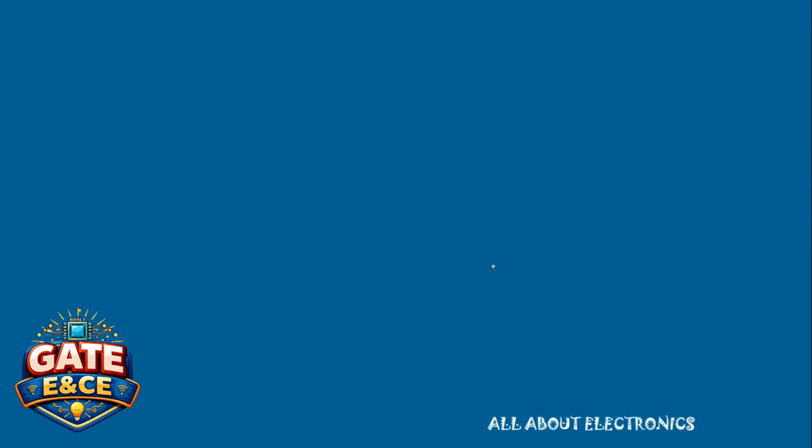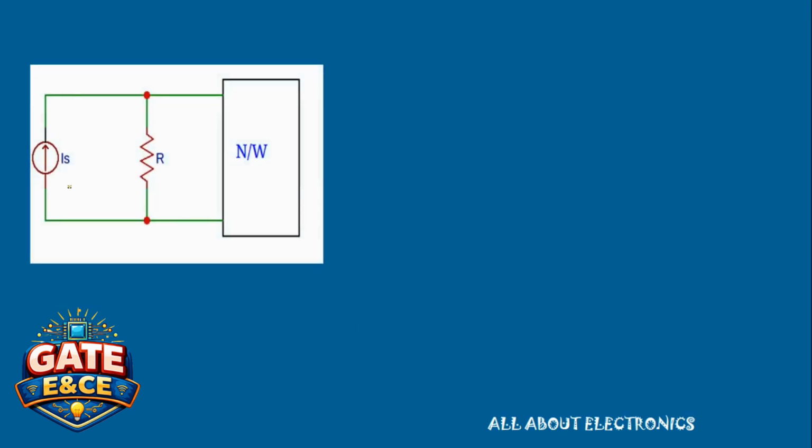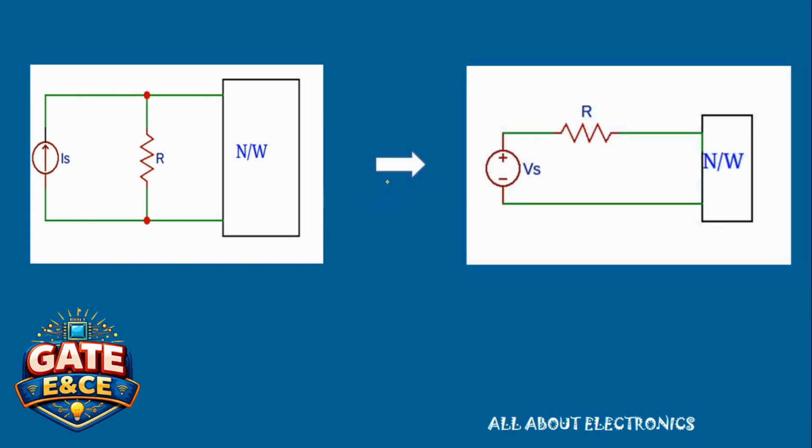Likewise, let's say we have a current source Is with a resistance R in parallel in any network, that can be transformed into the voltage source Vs with the same resistor R in series. And the value of this voltage source Vs is nothing but Is into R.